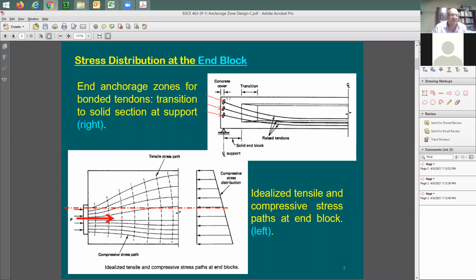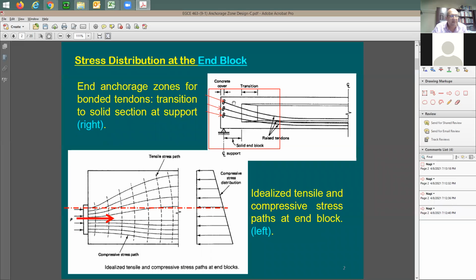Now, these high compressive stresses are going to be causing some trouble here, because all of a sudden you're going to put all the stresses at the end. This is where you transfer the force. Whether you have pre-tension or post-tension, transfer of the force is going to happen in this location. I'm going to say roughly in this area. And this is the reason that you see this piece to be solid, right? See, this is solid here. And right here, if you cut the section, it's going to look like an I-beam. So in here it's going to look like an I section, and here it's going to be a rectangular section. So why do we need this rectangular section? Because we have high compressive stresses at this place, and we need to provide some reinforcement to prevent cracks from happening at this location.